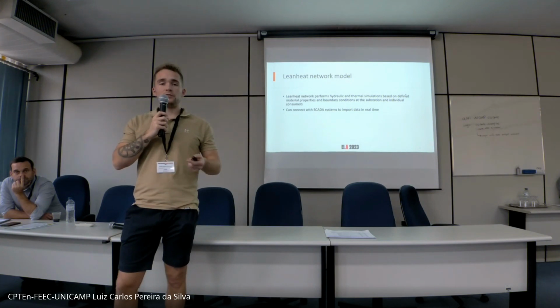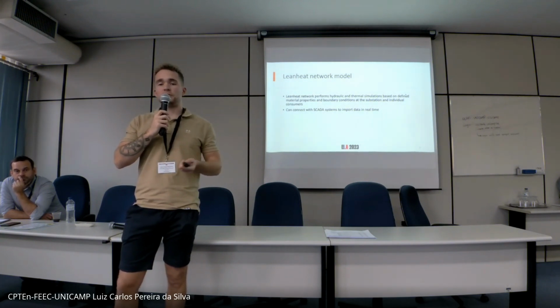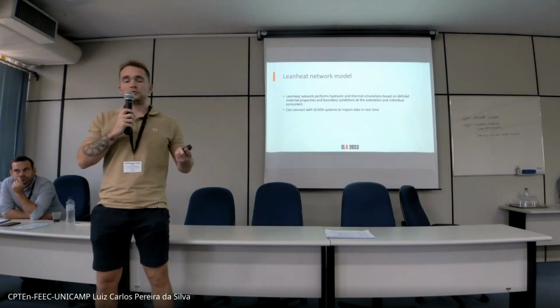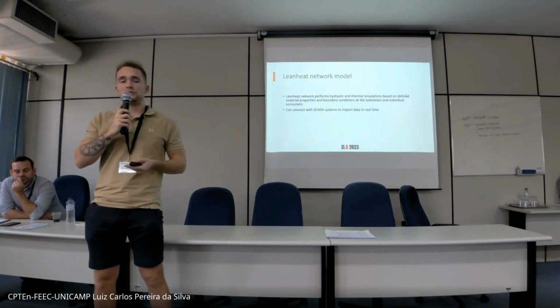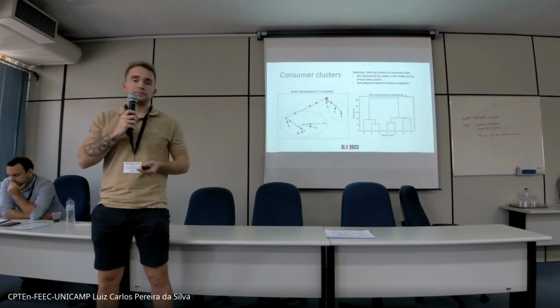In the scope of this paper, we used the measured supply temperature and return pressure at the substation and pressure change at a critical node in the system as boundary conditions for the substation, and for the individual consumers we use the return temperature and the heating demand.